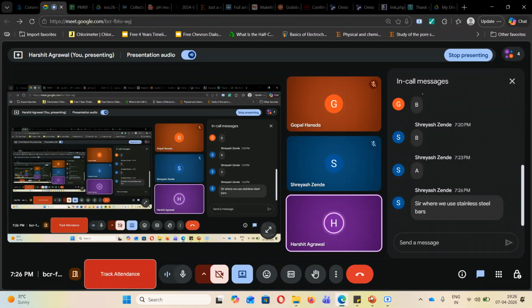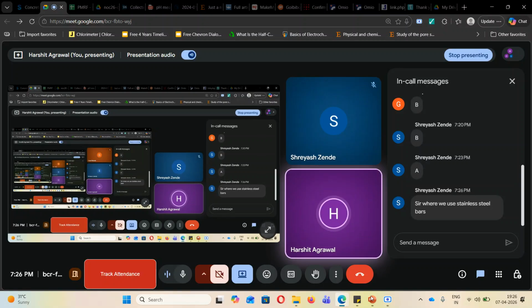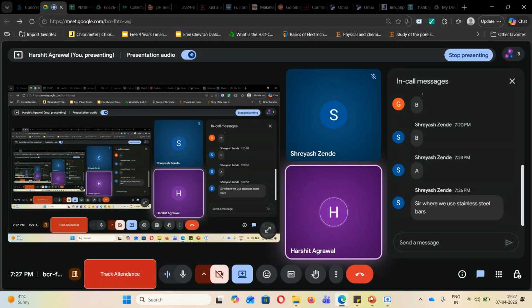So stainless steel bars are generally used if we have a good budget in construction. We know stainless steel bars are really expensive, but suppose we are doing some construction very close to marine exposure, like very close to seashore, where a normal steel bar won't survive for long, then for such cases we may prefer using a stainless steel bar.